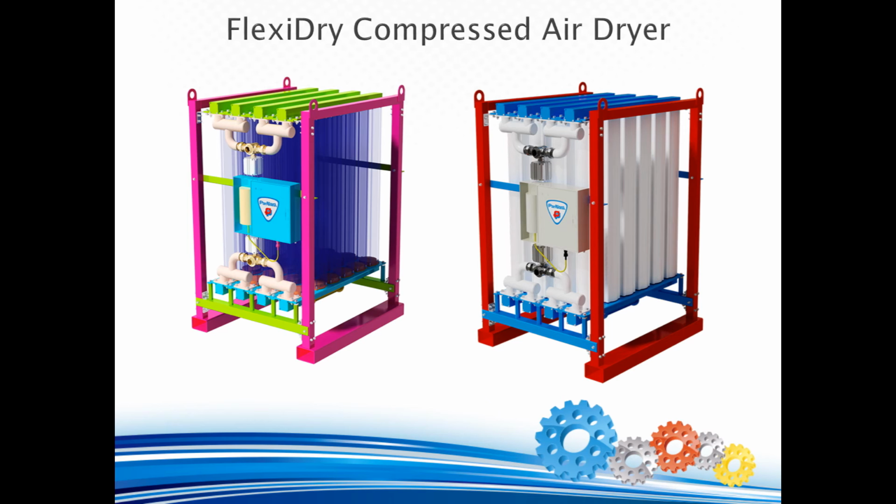To get the FlexiDry model shown in this slide, we require 2 sets of Flexi 6U module pairs for a total of 24 vertical tubes. Each pair is rated at 410 CFM for a total flow rating of 820 CFM. In this 820 CFM model, we will have two sets of 12 vertical tubes connected together via gang manifolds at the ends, with each set of 12 tubes alternating between desiccant regeneration and compressed air moisture adsorption, with sequencing controlled by a process controller housed in the control panel. System operation is either via 110 to 240 volts AC mains or rechargeable 12 volts DC battery supply.